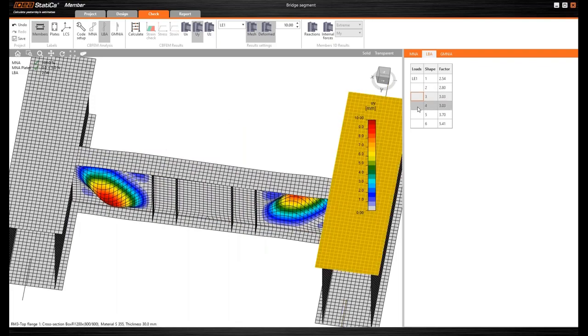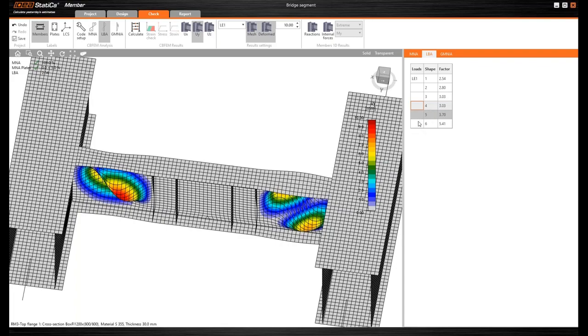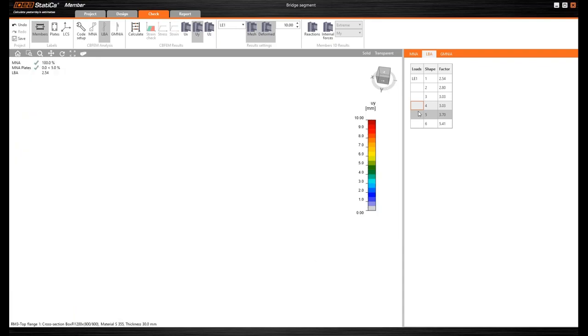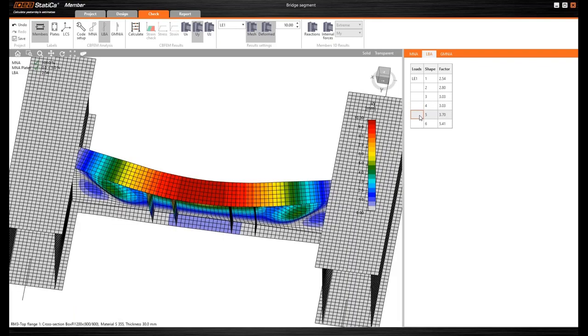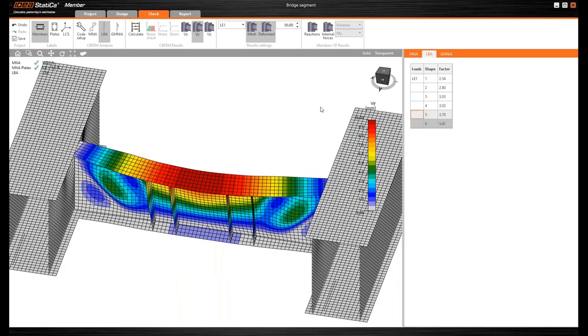In the third eigenvalue shape, we have the same thing. In the fourth, with the same factor, it is the same, but with a different side. At the fifth buckling shape, we have only the lateral torsion stability loss for the transversal beam alone.